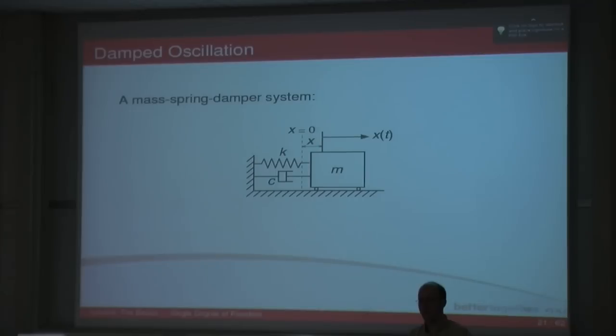And obviously at that point, when the thing comes to a stop the other side, there's no damping force, but there's a spring force trying to bring it back, and so on. And what will happen is, as the damping is being applied, obviously with the spring we're getting the energy back, because we're compressing the spring the other side. Okay, with no damping, you let go, the mass overshoots the equilibrium position, and all that kinetic energy in that mass is getting put back into the spring as potential energy. Great, and then going the other way, it will convert that potential energy back into kinetic energy and so on.